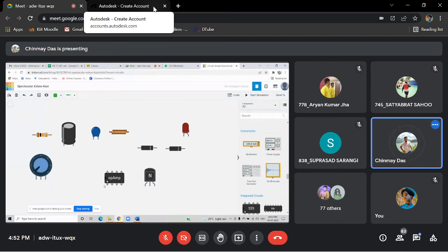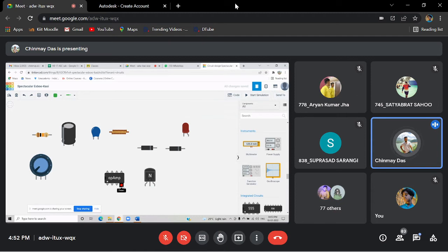Okay, so I see there's a dot mark here. The white dot on that side terminal is pin number 1. In the software, which pin is the input, output or power is directly written. But practically, you have to remember for the IC number and pin number which pin is input and which has to be connected to ground. So pin number 1 to 4 you have to count from this. Opposite of 4 will be 5, then 6, 7, 8, 9.